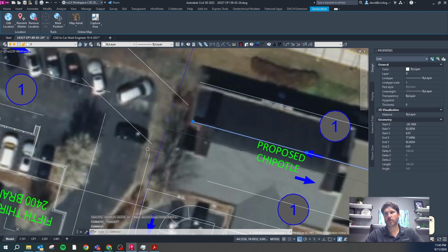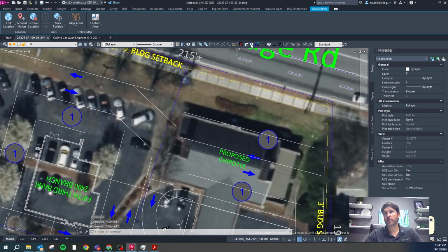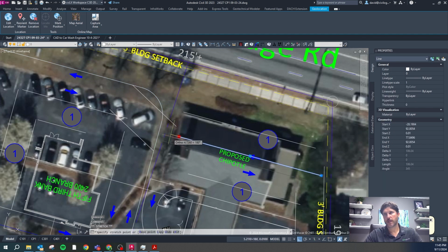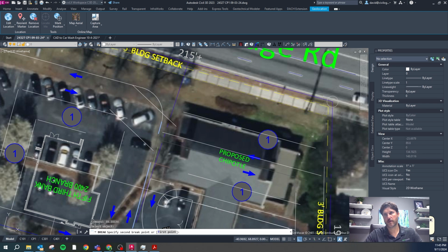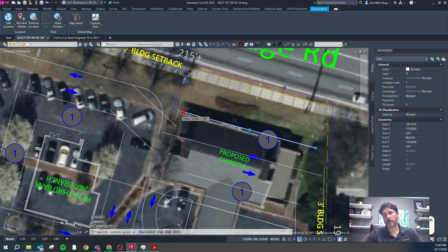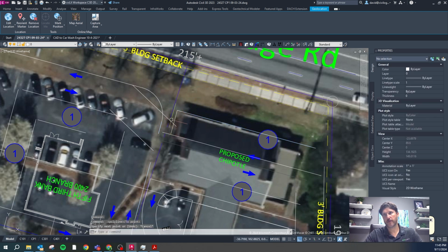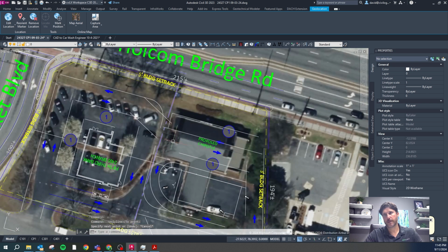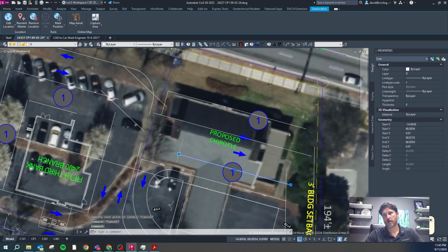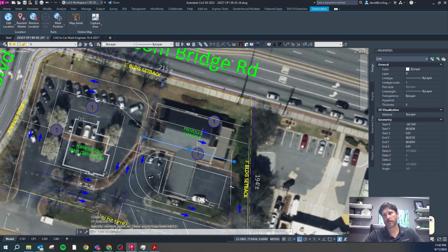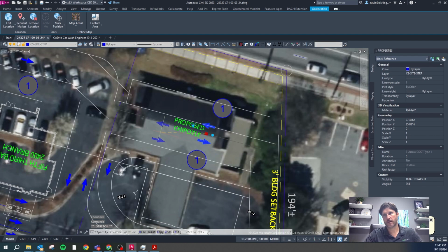What we could do is, I like to use 20-foot radiuses a lot in parking lots. It's just kind of a good number. So we could take this guy to there, and then this parking could go out like that. And so you'd have an island there, and this would basically be like a T intersection into this road. And then it doesn't feel quite as weird. So that's actually a pretty reasonable thing there. So let's go with that.